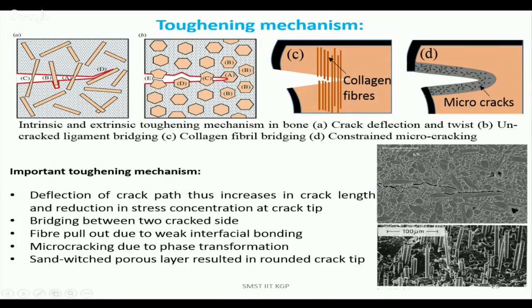Here I can see one of the particulate composites, a very nice example. In this particulate composite you can see one big grain, and in this big grain the crack follows almost a straight line for some time. This is not desirable. So when you are designing the material you need to control the grain size.